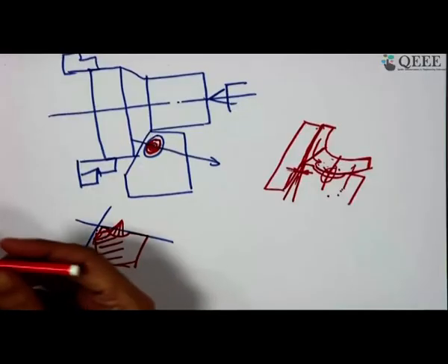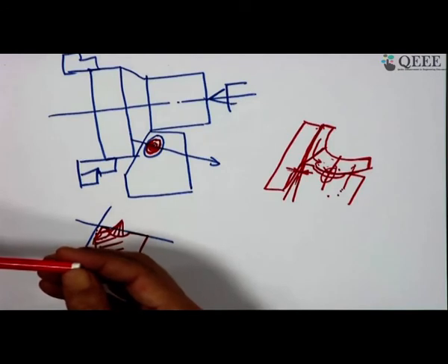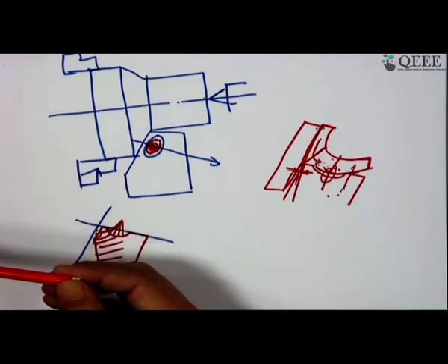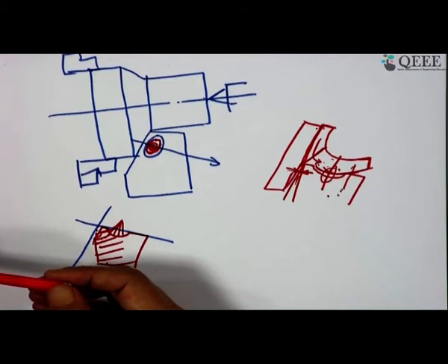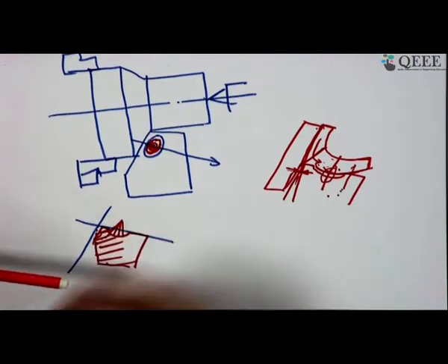But again, tungsten carbide itself is a cutting tool, so it needs shaping and sizing. When these issues come into the picture, one has to go for making that shape. Suppose it is square shaped, or in the form of a shaft. It is not only for shape; you can have a cylindrical piece of tungsten carbide, and for many structural uses also tungsten carbide can be used, not just for cutting tools, and in that case it is mostly done by grinding and then lapping and honing.